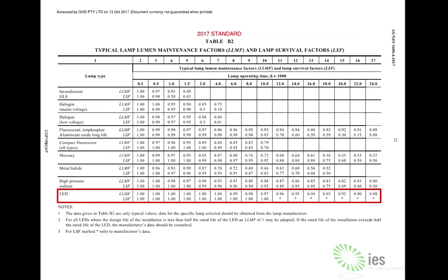If you run it, or 10 or a million hours, that's when you run it at a really low current. But the moment you actually start to use the chip, that degrades, and the other bit is they do have curves. But again, once you include for cooling and how they actually intend to run it, that changes as well. So there's plenty to consider there when it comes to how you get your data and if the data is correct. Always validate your data with a sanity check and what you're expecting to see.